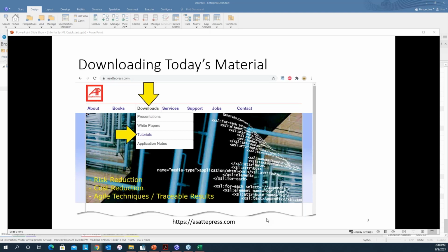But the point was to adapt the diagrams. Instead of 22 diagrams, SysML only has 9 to be a little simpler, and to present especially things like blocks and a few others, like parametric diagrams, which are available for doing simple simulations of a system that weren't in UML. So it is more oriented towards designing mechanical, electronic, and software systems, not just software.